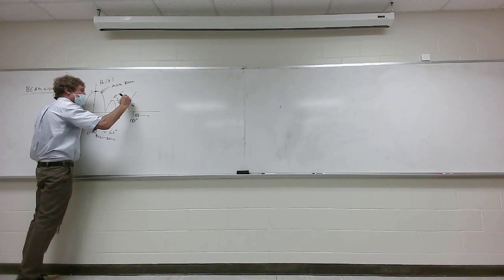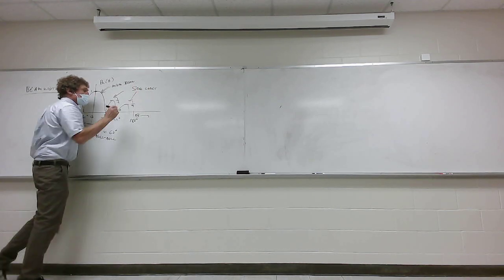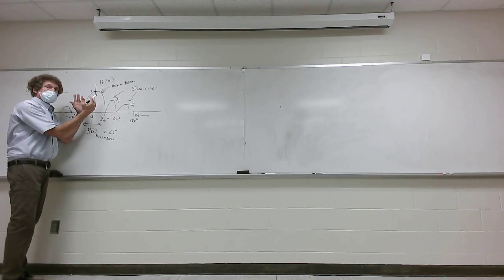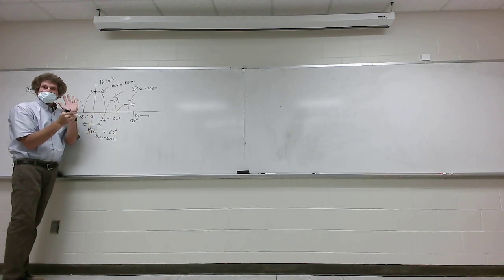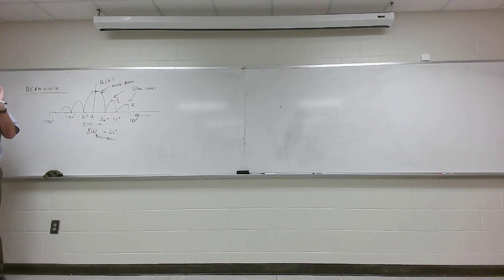These are called side lobes. Now, side lobes generally are unwanted. You wish we could get rid of them, but you can't. You can reduce them, but you can't get rid of them. And the tighter or the narrower you want that main beam, the more of these little guys sprout up. It's just a reality of antenna design. You can't help it. So what they do is try to minimize them. There are tricks to that, and that's in Riggs's antenna course. It's actually quite interesting, some of this stuff.